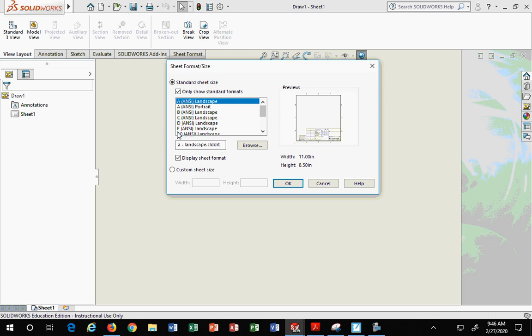And then they're wondering why nothing will print and things are erroring out. That's the reason. So your output printer is what dictates which size you select here. Please keep that in mind. In our case, our printer in this room goes with A size paper, which is 8.5 by 11. Nice part is it shows you that information right here. B size shows you right here.